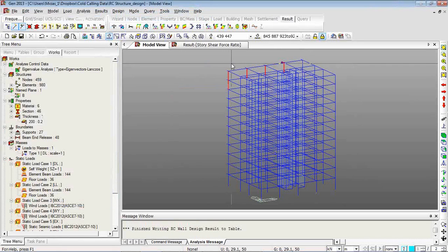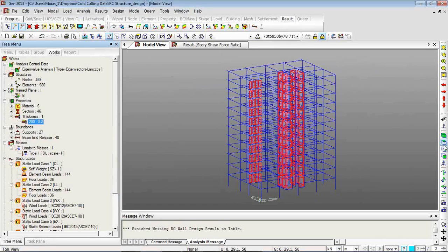You can also design for wall. I haven't selected the wall element right now, so this is how it works: you just select the element. By clicking on wall design, MIDAS will give you the PM interaction curve as well as a detailed report on how the hand calculations were done, and this can be used in the verification features.